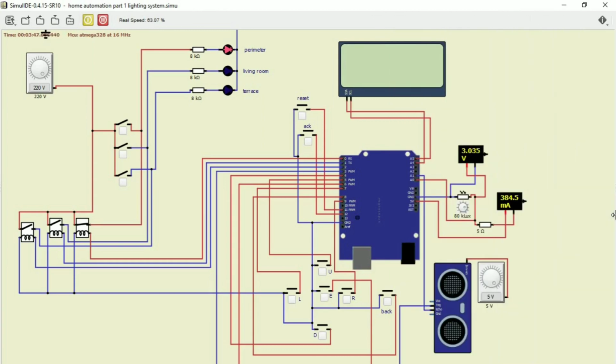and our LCD is blank, and we need to restart that system to load. And as usual, when the system is restarted, everything will turn into default in manual mode. And right here we have to change the perimeter light into auto mode, so that we could simulate again the light condition, and we will see if it turns on at 3 volts.